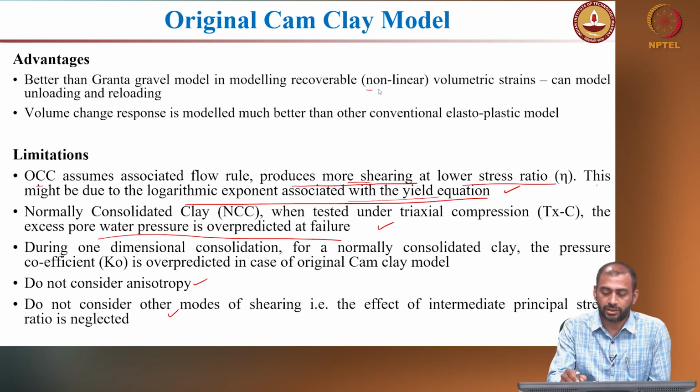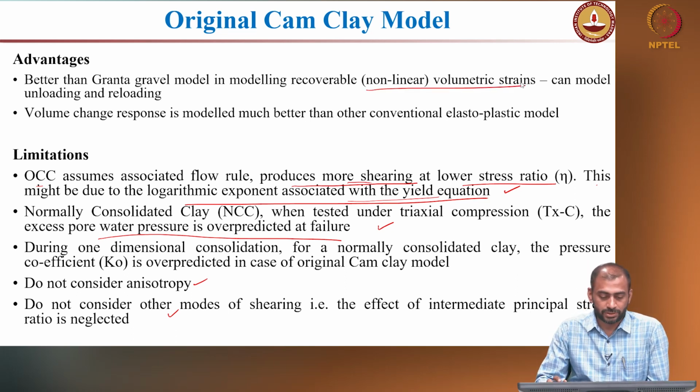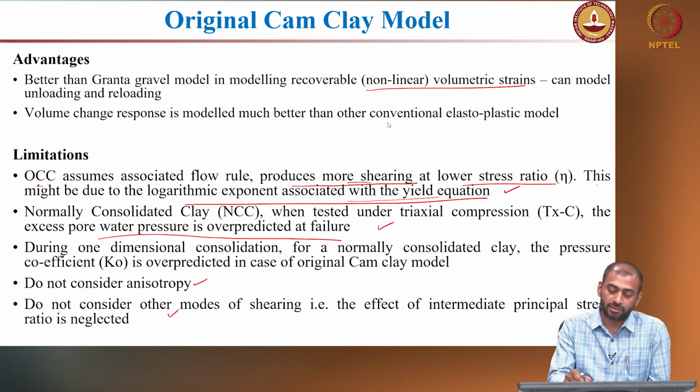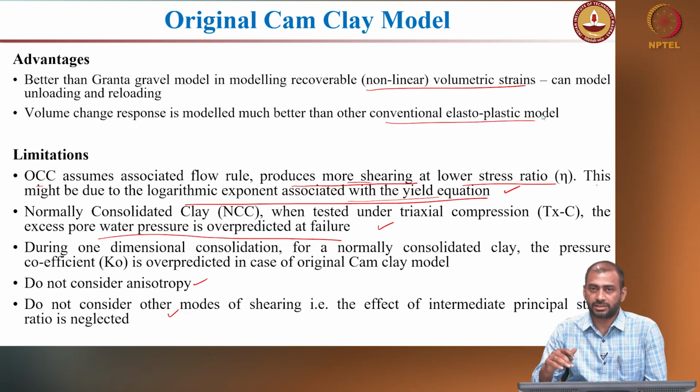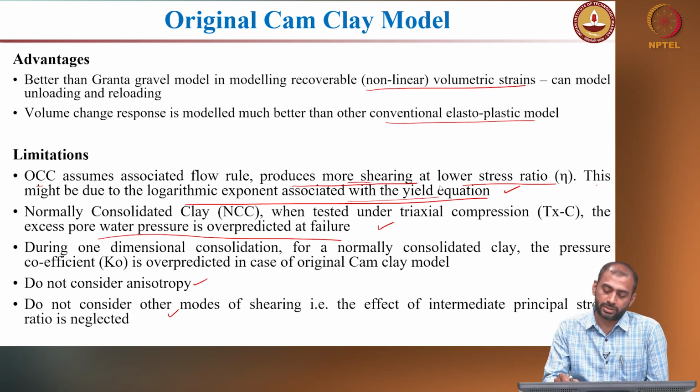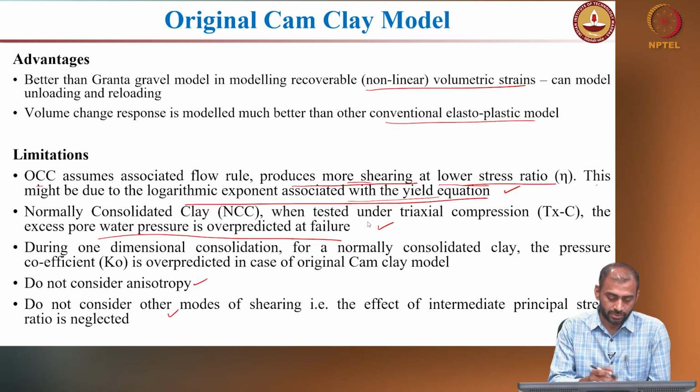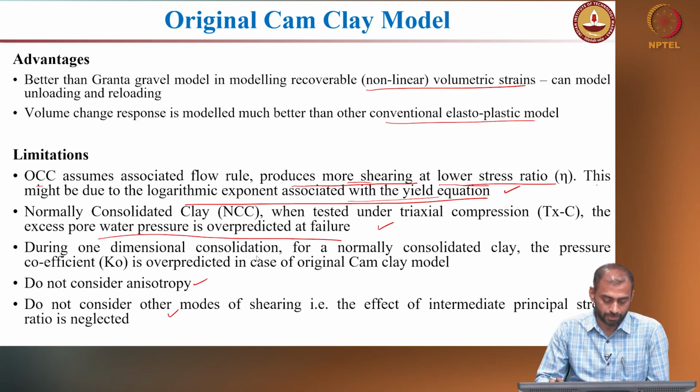in predicting the nonlinear volumetric strains, and the volume change response is much better than the conventional elastoplastic models. When you use elastic perfectly plastic models, the volume change response is not well predicted, especially the dilation, whereas the original Cam-Clay model was able to predict the dilation. However, at lower stress ratio it produces more shearing, and also it over predicts the pore pressures. So, these are the issues with the original Cam-Clay model.